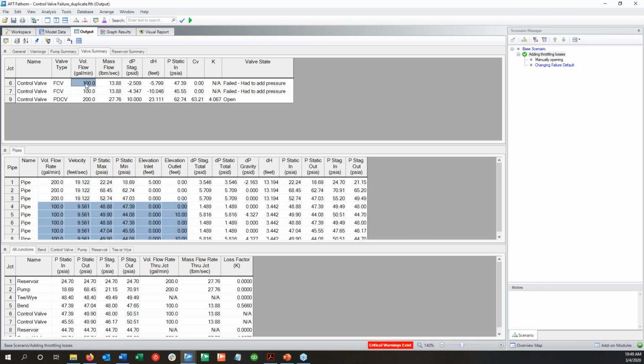So why are we still meeting this volumetric flow rate? This is where that always control checkbox comes in. If that checkbox is checked, no matter what, regardless if it can control or it can't, it's going to try to add pressure until it meets that flow rate. And so that's why you see things like, oh, I got a negative pressure drop across my valve. Looks like it's adding pressure. And so that should be a red flag in your mind also.